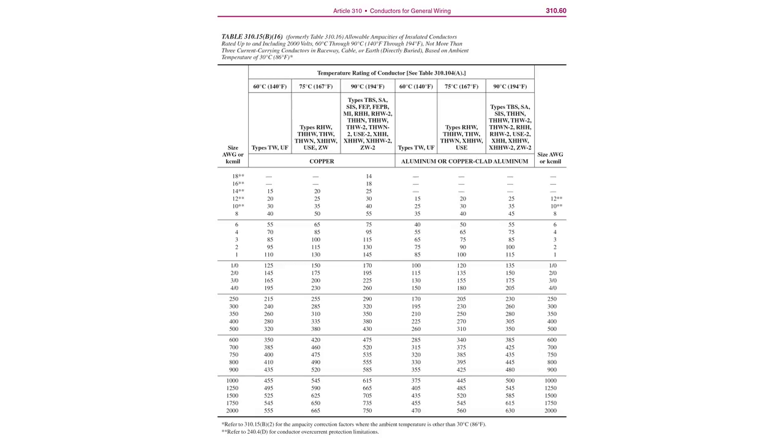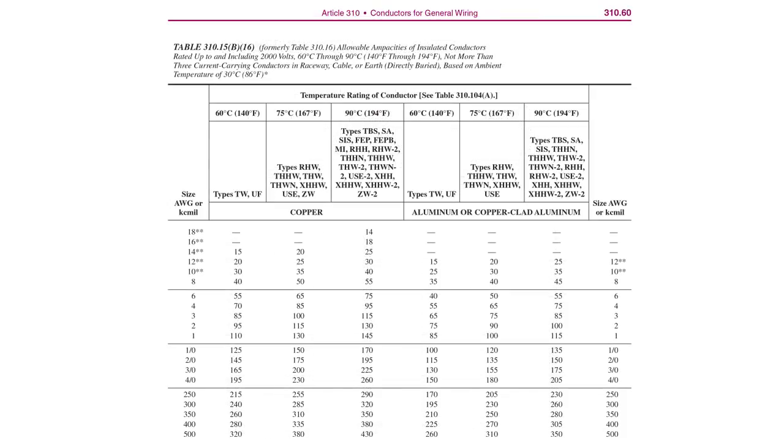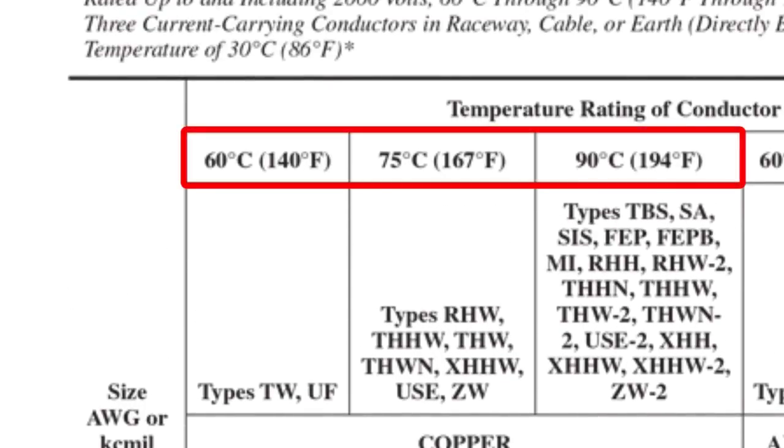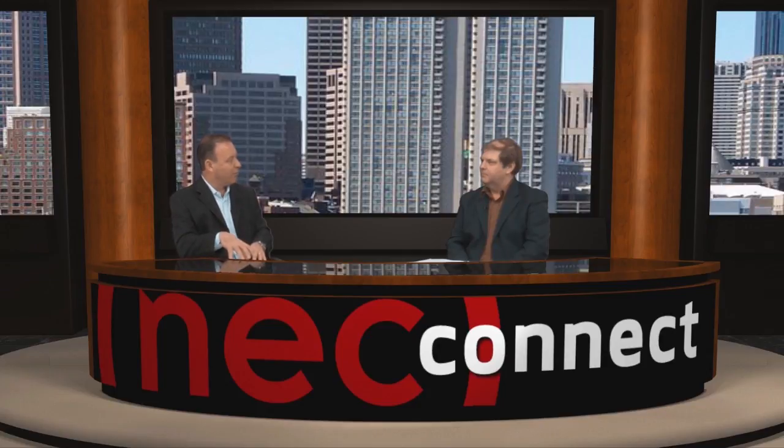Right. So if you look at this table, if you had a 60 amp load and you went to this table, a 4 AWG copper conductor would suffice, or you could use a 6 AWG 75 or 90 degree conductor. So as long as you met the conditions on top of that table, that's what you would have for a conductor, a 4 or a 6, depending on which is the insulation. So again, it shows you that it's the temperature that's really a factor, not the current on the conductor. So that's really the basis for these tables.